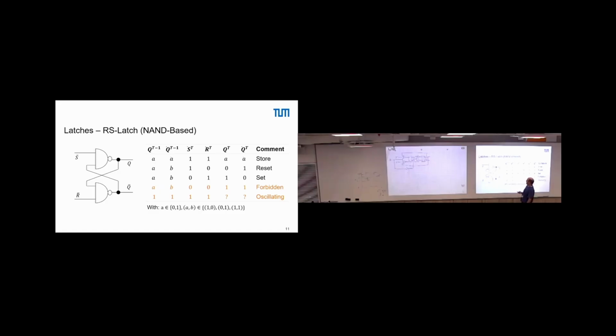Now if we go into this reset, so we pull this here to 0, this here to 1, then in a time simulation over time, first the Q bar will go to 1. If we go here from 0 to 1, then this here goes from 0 to 1. In this first virtual time step, this here remains at 1 because here is 1, 0, right?